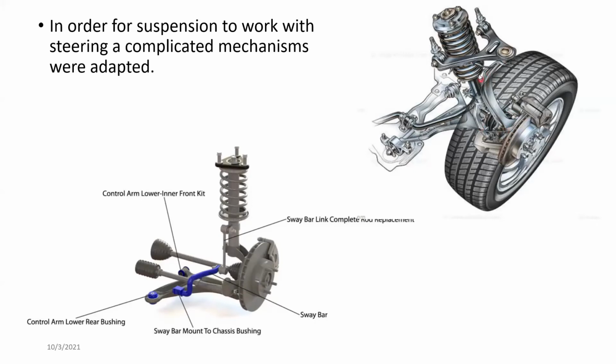Then the suspension arms, or the hydraulics, sorry, struts, are connected to the knuckle over here. Instead, the coil spring and the strut are connected to the knuckle directly itself, right? So there are small differences in these, but these things come because of how the vehicle's suspension is going to react, right? We'll discuss this a bit further in the suspension part.